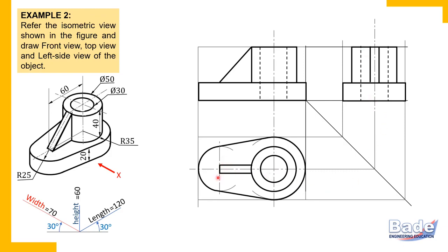Instead, 10 millimeter width of this plate. Width is vertical in the top view, appears horizontal in the side view. So you can measure 10 millimeters horizontally here independently instead of drawing this projector. So measure 10 millimeter, and between these two end projectors, this horizontal projector and this horizontal projector, you complete that rectangular strip in this manner.